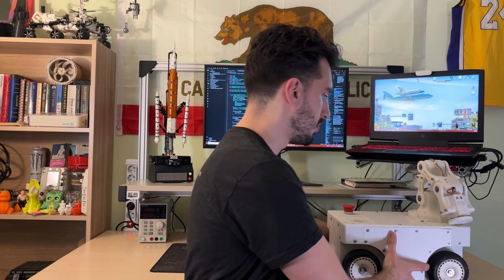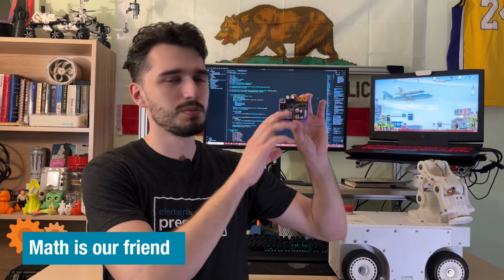Now, the thing with PIDs is that they're extremely timing critical, so we need to run them at lower level hardware, meaning microcontrollers, and to get them as fast as possible. So we're talking about millisecond or microsecond level precision, something that we can't achieve with single board computers like a Raspberry Pi. How do they actually work? Well, I'm gonna show you that now through just a bit of math, don't worry, and then we're gonna see a practical example with this board here on what PID tuning is and how they work, to see if we can achieve some good results in controlling a motor.